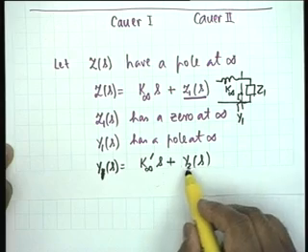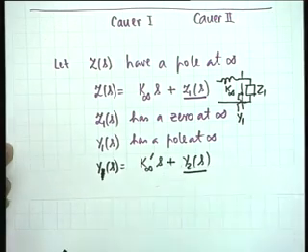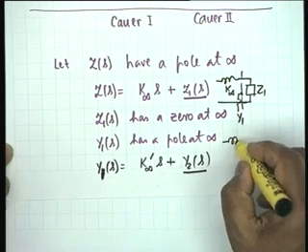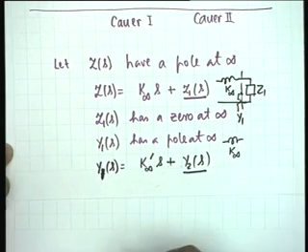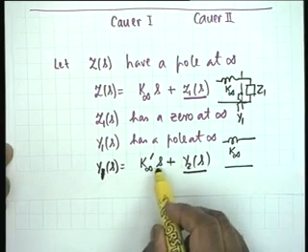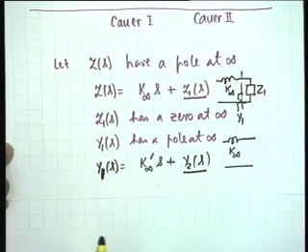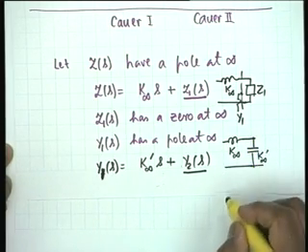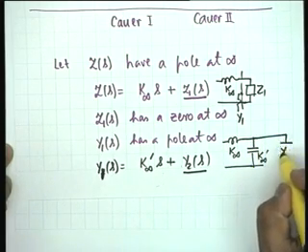Then Y2 must also be LC, and the partial realization is an inductance k infinity. Then from Y1 you have taken an admittance of k infinity prime S, which corresponds to a capacitor, and the value of the capacitor is k infinity prime. The rest of the admittance is Y2.